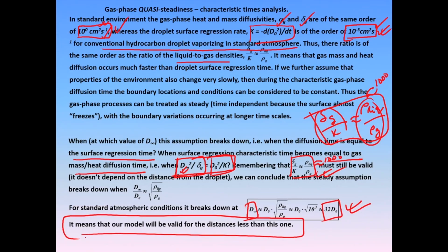So, this d square law is very powerful, but it comes with its own caveats, which are the assumptions that we have stated, and we have assumed that it is a liquid vapor. Of course, if the difference between the densities of the liquid and the gas is very small, for example in supercritical cases, then you cannot assume quasi steadiness. So, be prepared to understand what assumptions are applied and why they are valid. That is an important part of this argument.